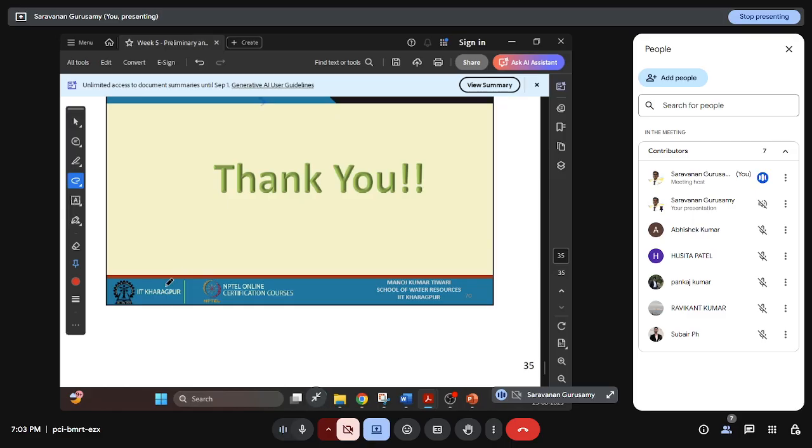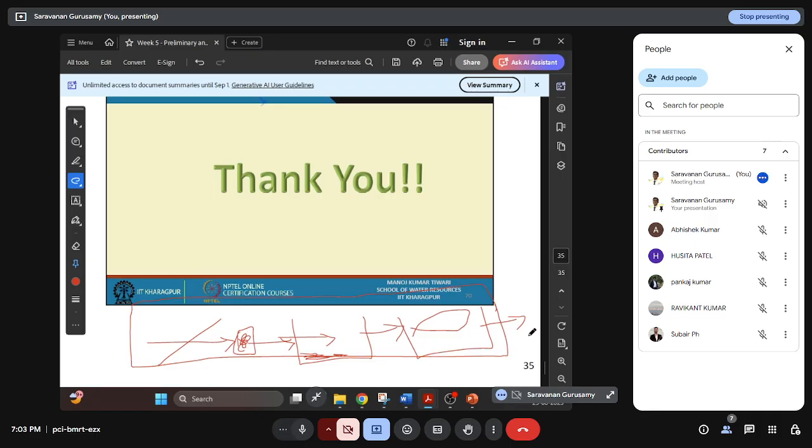You got it. So today we have discussed the screens. Water is flowing through the screen, and then the accumulated grit will be ground. Then it will flow through the grit chamber, where the larger particles are removed. Then it passes through the sedimentation tank of circular or rectangular shape that removes the suspended particles. All this is considered as preliminary or primary treatment. Then it will go to the secondary treatment. If it is simple water treatment, this much is enough. We can disinfect and we can supply. If it is wastewater, we need to have secondary treatment and more. You got it? Yes.